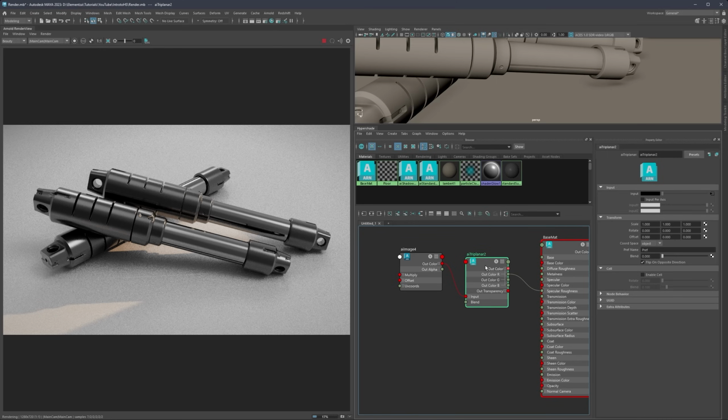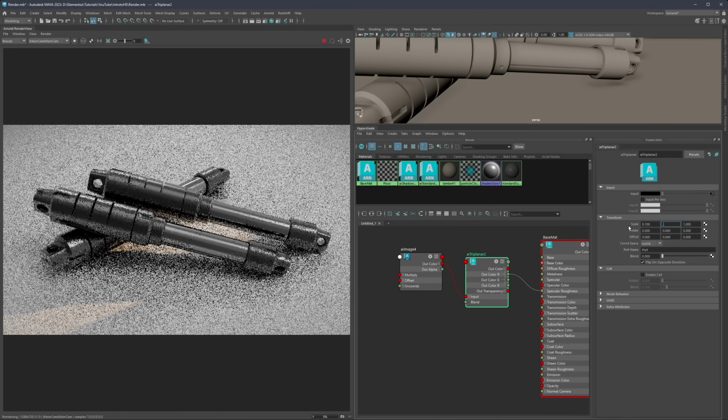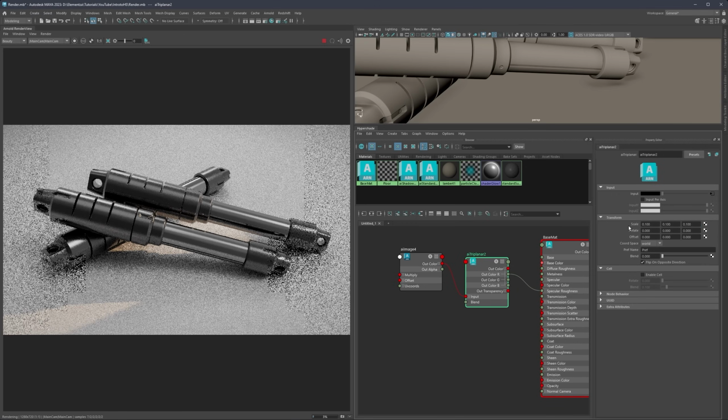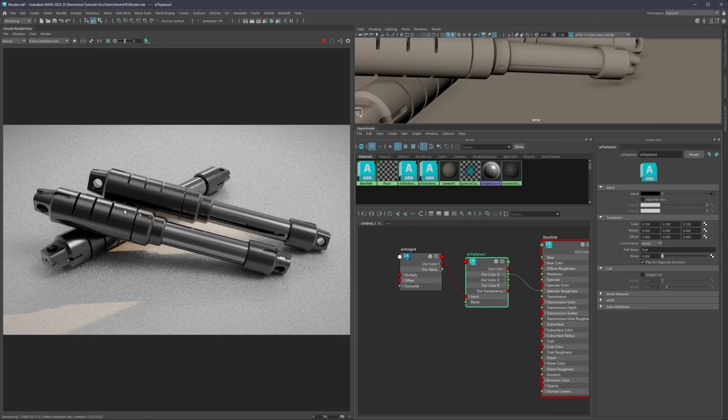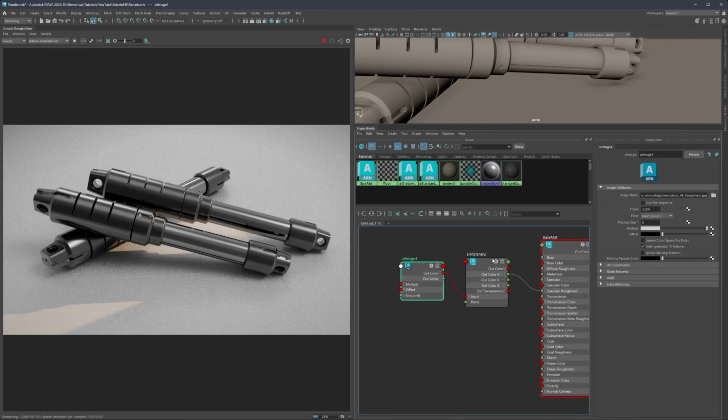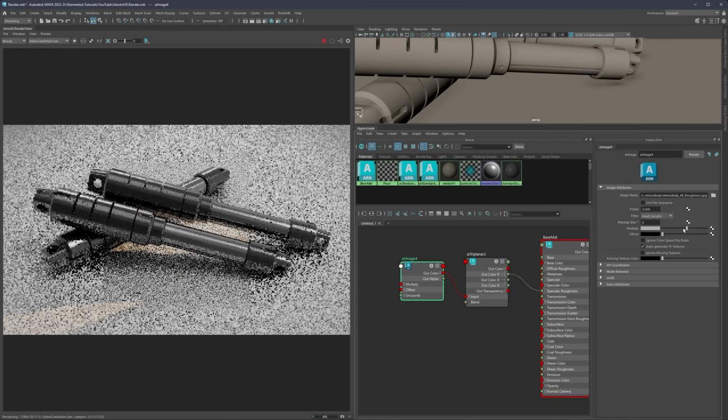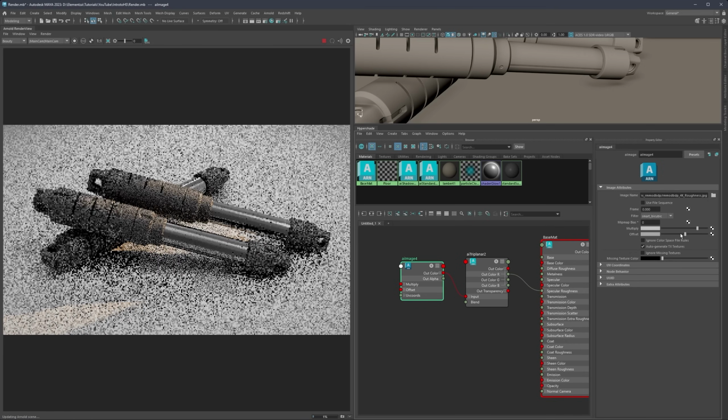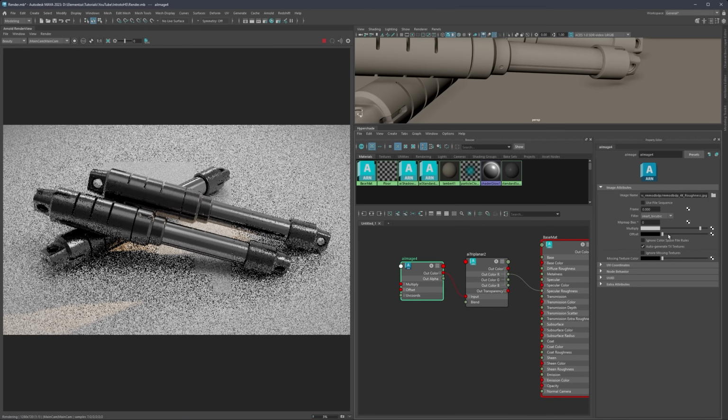By default, triplanar might appear again too big, so you won't see much. But if we change the coordinate space from world and scale this all the way down, because usually Megascans textures will appear slightly too large, we should now start to see some kind of imperfections on the surface. There are also additional things that we can play around with. For example, you will notice offset and multiply.